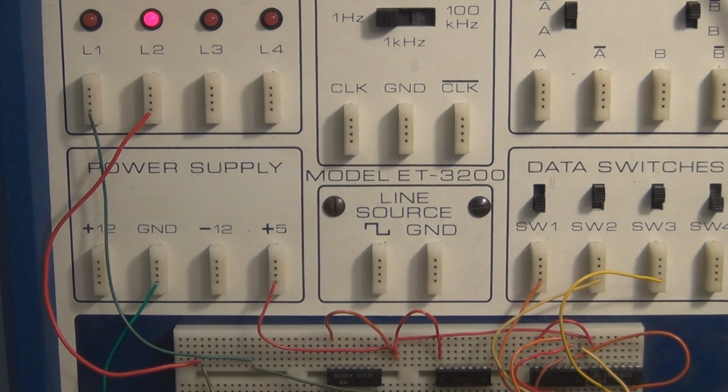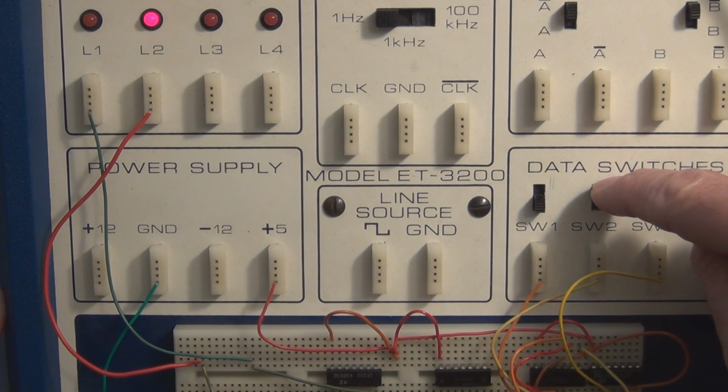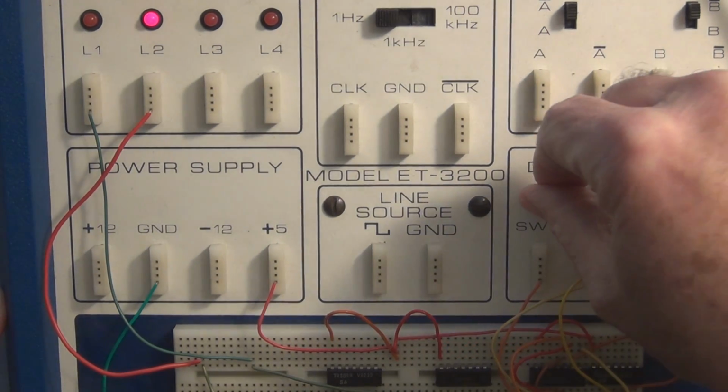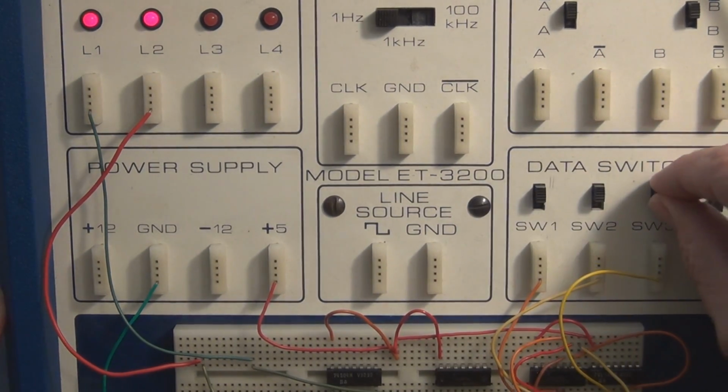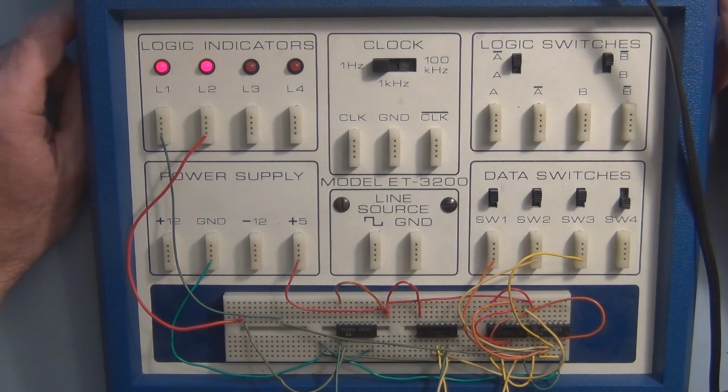And that's correct. And the other combination is when we have 2 bits that are 1, that are the inputs from the 2 registers, and a carry of 1, which is a 1 and a 1. So this is all working correctly. So that's the full adder circuit, and you just string those together.